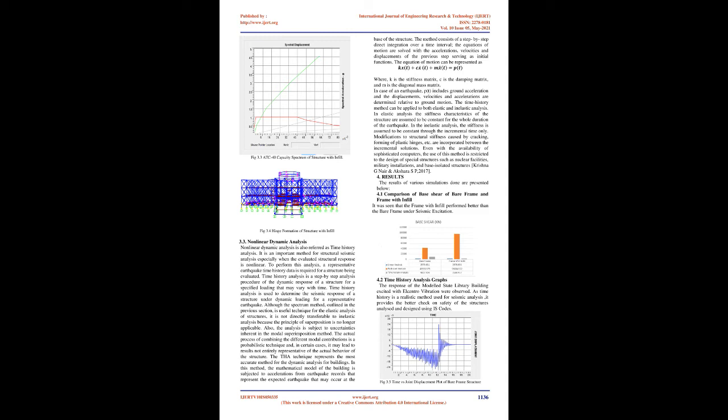Pushover analysis is a static nonlinear procedure in which the magnitude of the structural loading along the lateral direction of the structure is incrementally increased in accordance with a certain predefined pattern. It is generally assumed that the behavior of the structure is controlled by its fundamental mode, and the predefined pattern is expressed either in terms of story shear or in terms of fundamental mode shape.